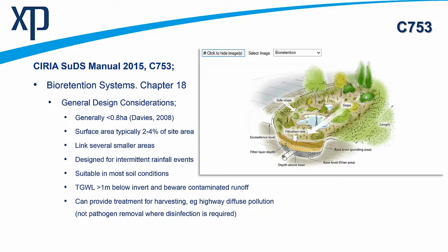They're designed for these intermittent rainfall events, so they're generally quite shallow. You could just have a 150, maybe 200 millimeter depth of water for, say, the 1 year return period, and then have a 500 millimeter depth on the surface for, say, the 30-year return period. It depends on what you're being asked to design in accordance with by your approving authority. So I'd encourage you to talk to the water companies. I'd encourage you to talk to the local authorities, the flood risk managers, and the Environment Agency at the outset of the design to get an understanding of their needs in the local area.